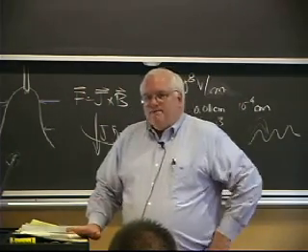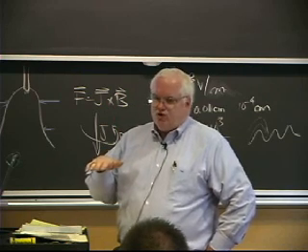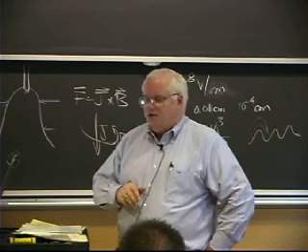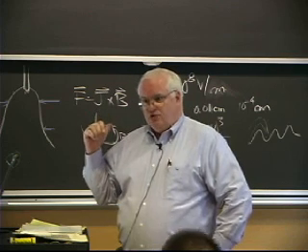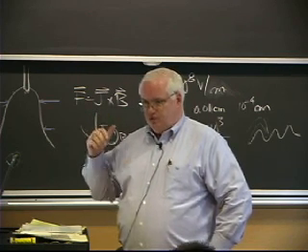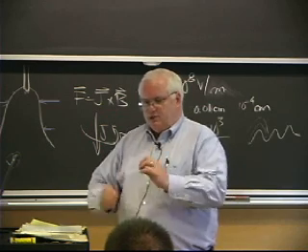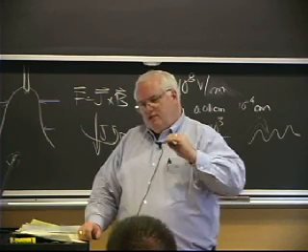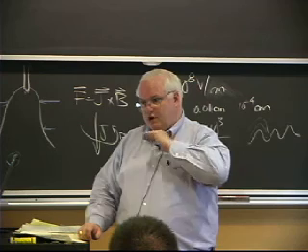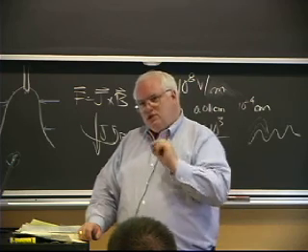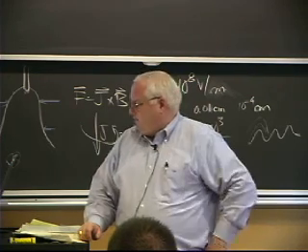It turns out we also know that on a liquid surface, a liquid metal surface where you have no asperities, it takes about another factor of 10 in voltage gradient to get field emission from the liquid surface. And in fact, as things get very, very close, sometimes the liquid surface, the electric field actually overcomes part of the surface tension. The surface tension wants to make everything perfectly smooth, and you actually can get little peaks in the liquid metal on the surface due to the electric field.